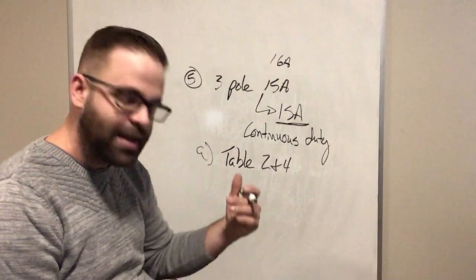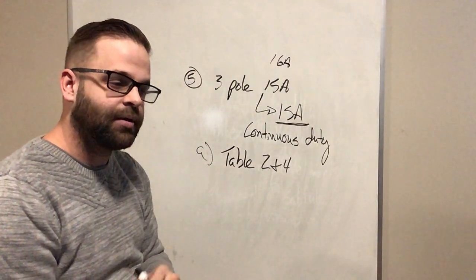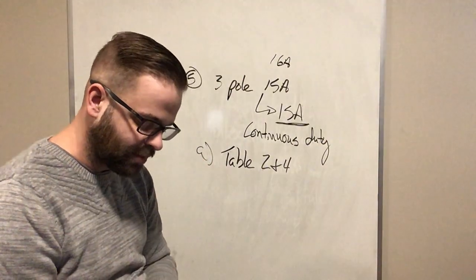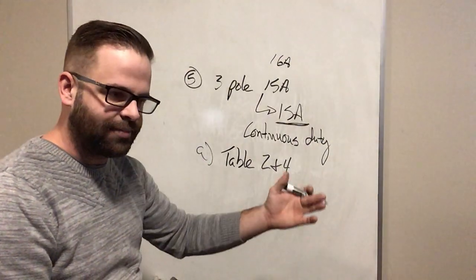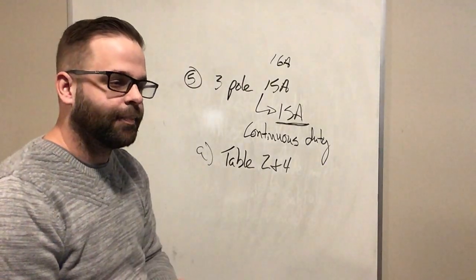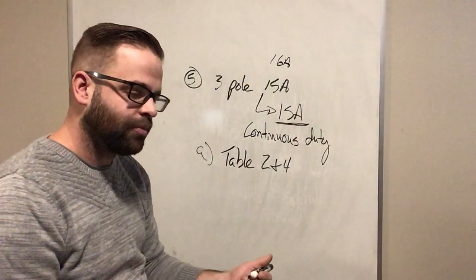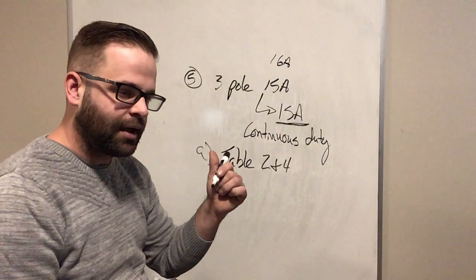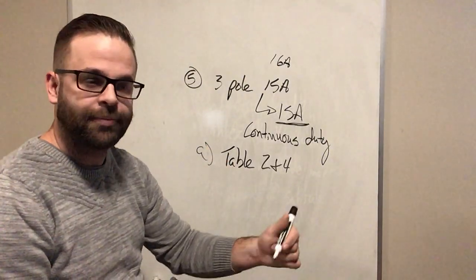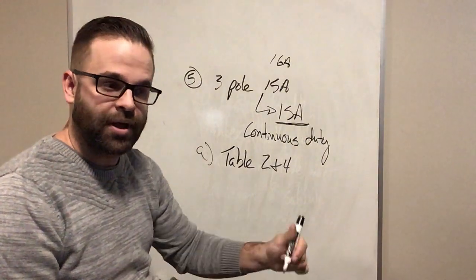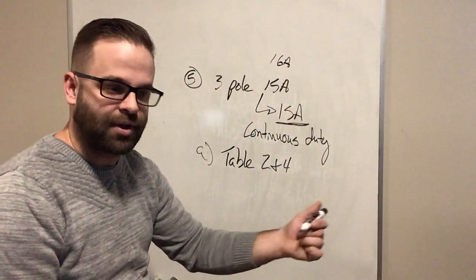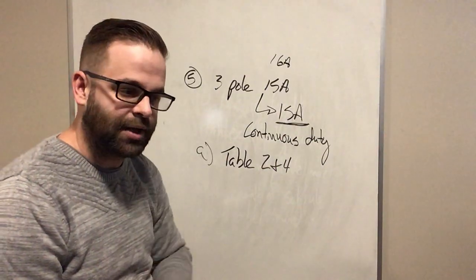And obviously if I'm exceeding the current draw on that wire, then that wire is going to overheat. So realistically, if I had said maybe a 30 amp breaker to start, a 30 amp breaker, and I've sized my breaker, so I've calculated a 30 amp load, I've put a 30 amp breaker in. I couldn't put a wire rated for 25 amps on that breaker because now I'm exceeding the rating of that wire.